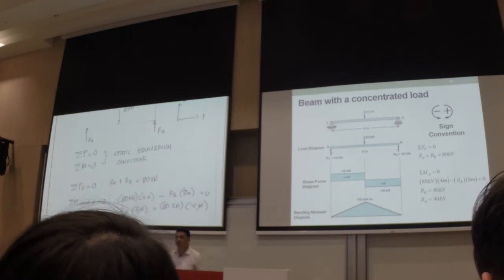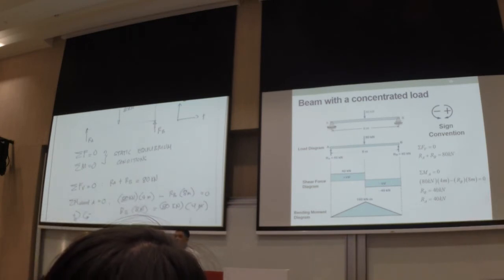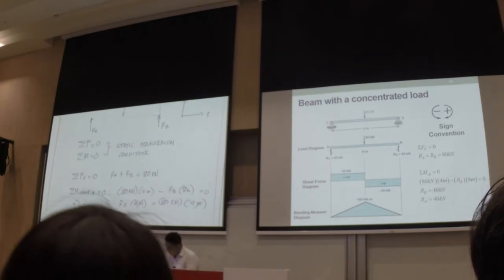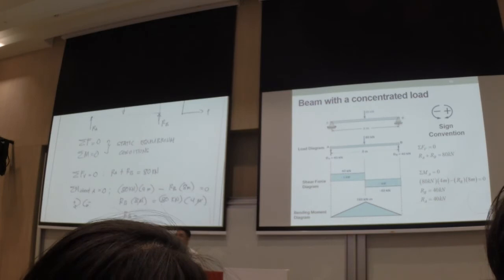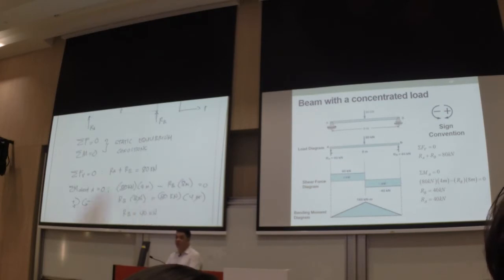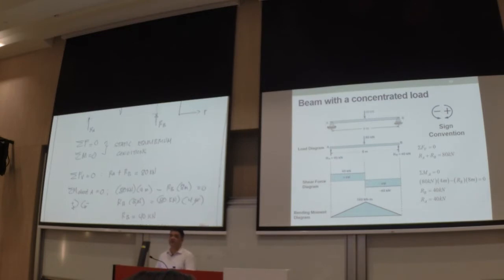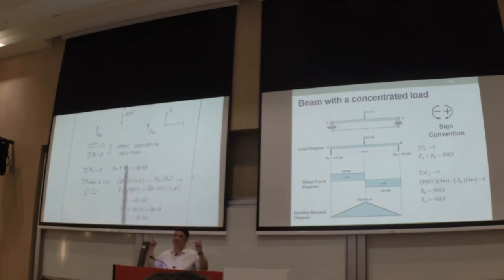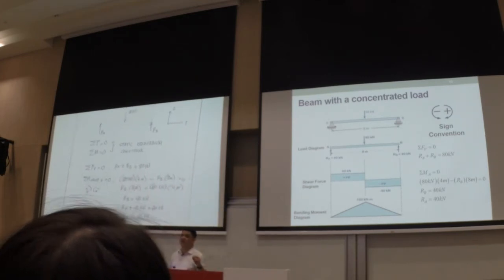So sometimes you can always check, you know, that forces will be in newtons, moment will be Newton meter, of course, a distance is in meter. So here, you have now your reaction force at B, that will be 40 kilonewtons. And of course, substituting this RB to this equation, you will now be able to have your reaction force at point A to be also 40 kilonewtons. Now anyway, by inspection, since this one is at the middle, you will know that the forces at the reaction will be the same anyway. And at least this one is just to prove that they are the same.